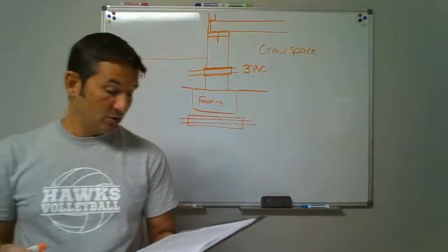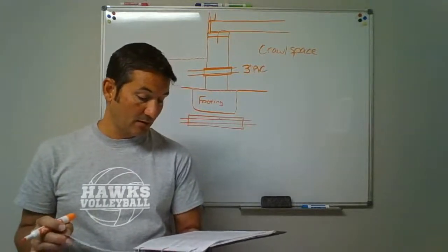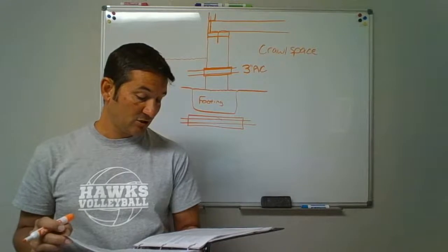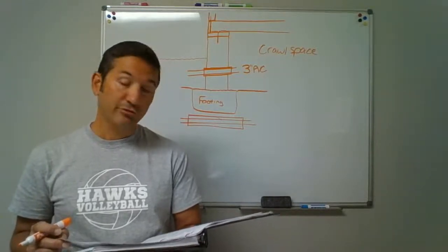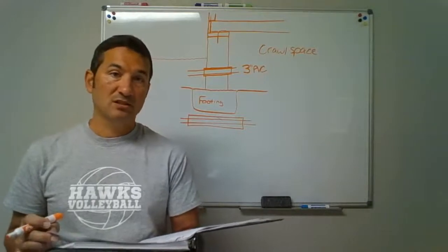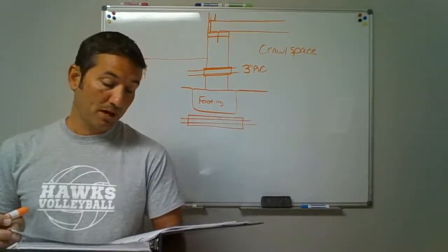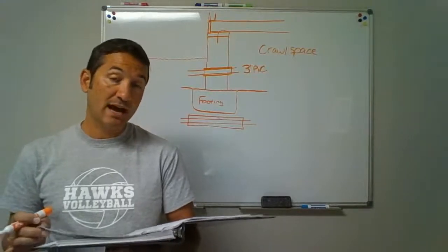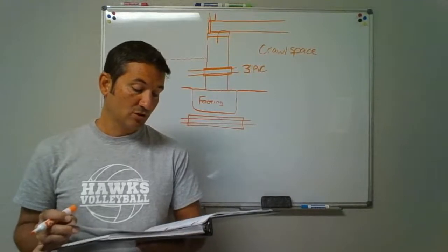code. So if you look at all the pipe sizes that they're labeled out there, it starts at a half inch, goes 1/2, 3/8, 1, 1 1/4, 1 1/2, 2, 2 1/2. Oh, 3. 3 is the pipe size we're sleeving. Go 2 pipe sizes larger. 1 pipe size up is 3 to 3 1/2, and then that's 1 pipe size. 2 pipe sizes goes up to 4.